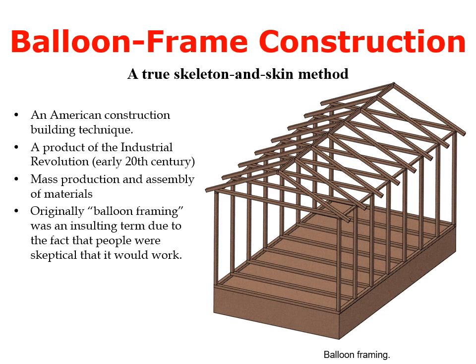So like it says, a skeleton and skin method, so that you have the wood framework in there, that's like the skeleton, and the skin, the sheetrock on the inside, and the brick or wood siding, whatever you put on the outside, that also helps to create a little more stability and to hold everything in place. So it all works together, and you're getting into the self-supporting systems.